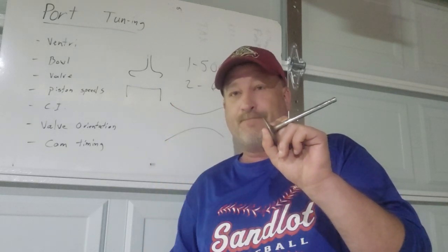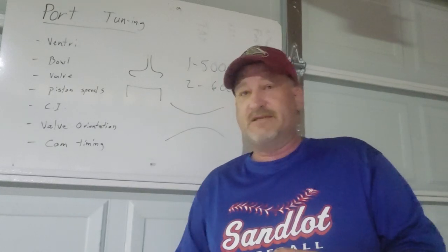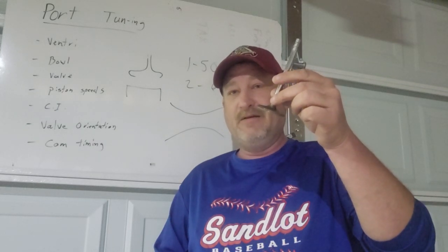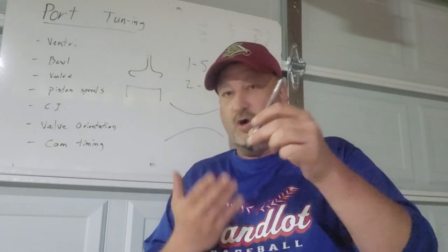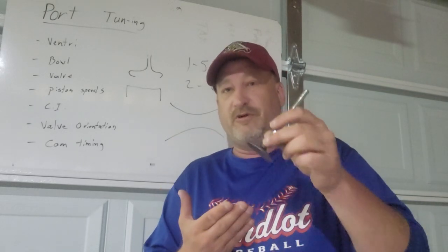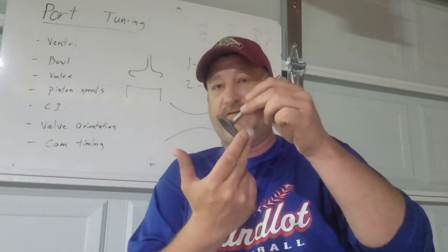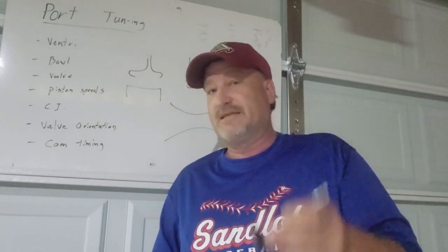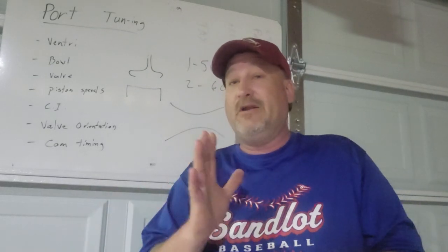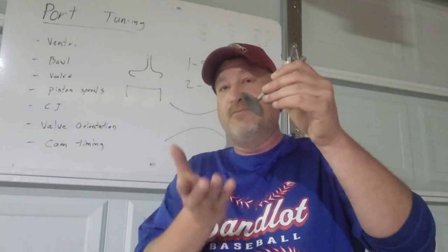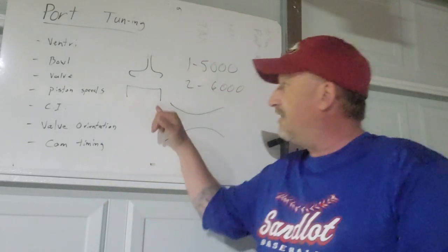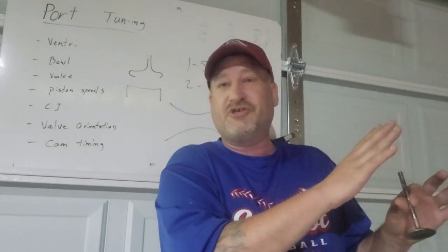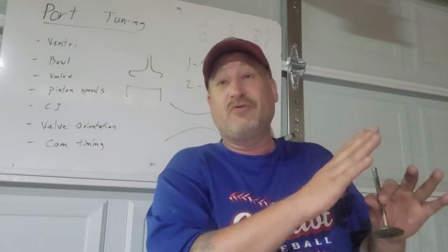The perfect 90 degree. Canted valve engines, if you'll notice the big block Chevys or Ford Clevelands, the valves are not canted to the point where they open towards a wall. They move away from the wall while restricting it, allowing a bigger portion of the curtain area to allow the air to flow through. But when the valve is closed, it's actually still operating. It's blocking off the intake charge, but as the piston is moving up on the exhaust, that pressure area underneath the valve is also directing the pressure towards the exhaust side of the combustion chamber,